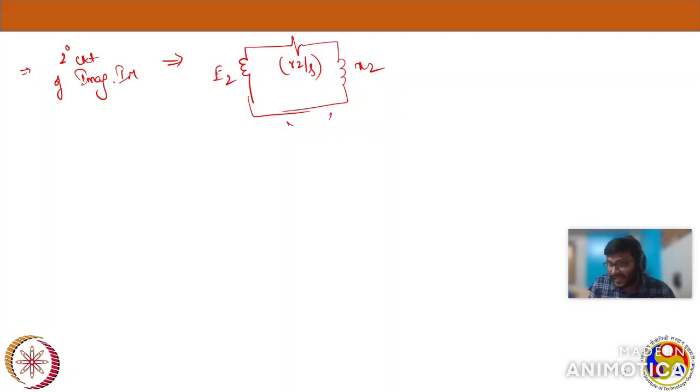Again you are saying SF. There is no slip in the induction motor here. In our imaginary induction motor, it's in standstill condition. Whatever frequency is in my stator, the same frequency will be in my rotor because there is no slip here. So again, don't get confused with these Fs.